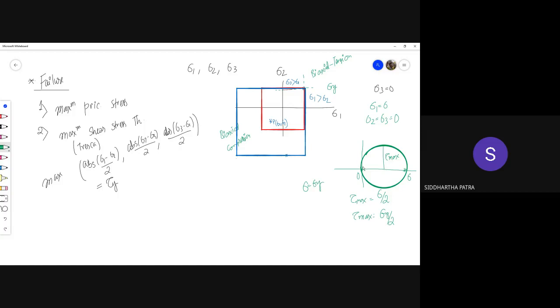Now, if we assume that this material follows maximum shear stress theory, more or less, or Tresca criteria, then failure only occurs when tau max is tau y. Which type of materials would follow such a material model? Since it is related to shear stress, you already know what type of material. More of ductile materials. So ductile materials can be approximately represented with maximum shear stress theory.